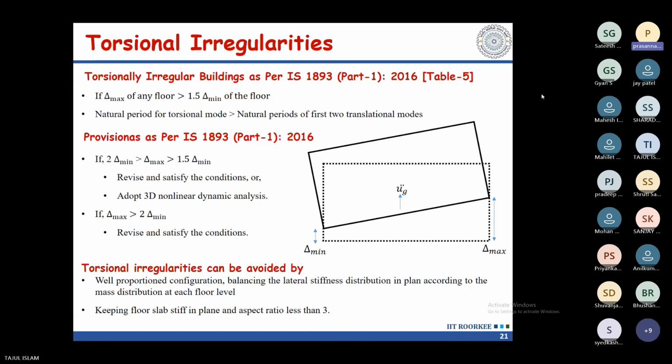See, capacity term means you are checking only plastic hinge formations, correct? Yes, capacity means we are checking the hinge formations, and whether the load applied is within the acceptable limit or not. Okay, that should be formed in columns first, then beams? Sorry, no. Yes, hinges have to be formed in beams first, then columns, and also your structure should have sufficient ductility.